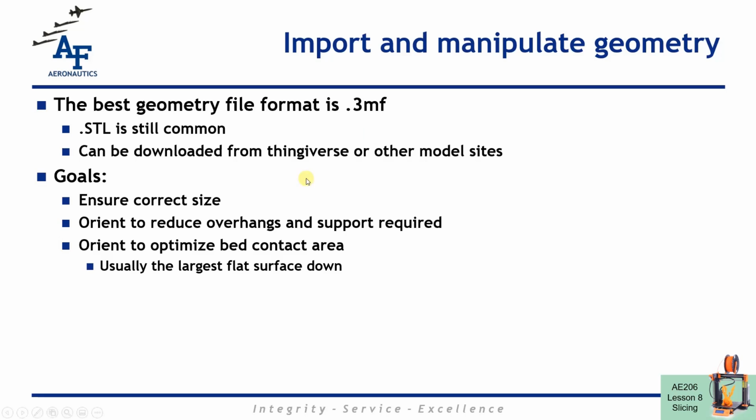From a big picture perspective, our goals for this step is to make sure that our geometry is the correct size, that there wasn't a units conversion issue from inches to millimeters or anything, that we orient the geometry in the best way possible to reduce overhangs and support, and that we orient in the best way possible to help it to stick to the bed during the printing process.